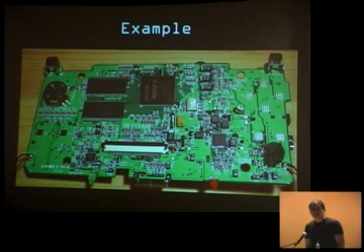So actually, I've never seen a circuit board with redundant traces or anything to confuse me, because the price of diffusing an electrical signal is that you sap the energy out of the signal itself. You introduce reflections, and it's hard enough to get the hardware working as it is. So these designers oftentimes won't take that risk. That being said, on chips it's a different problem, because they have so much wiring and routing resources. There are people who write compilers for Verilog that will compile it to a set of gates that are redundant, with multiple switching paths to defeat things like power analysis. Those are really frustrating for a reverse engineer. So yes, it's done at the chip level, but I've never seen it at the board level.